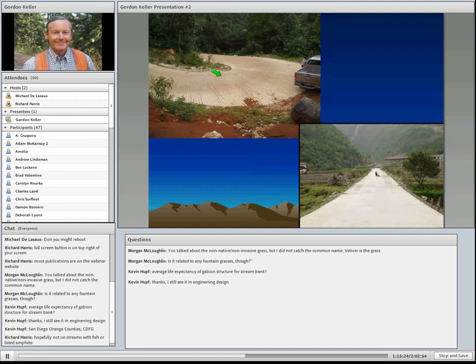Concrete has its place. Some countries use it a great deal. Its best application, for me, is either low water crossings coming through water or on steep grades. If you get into a really steep grade, it's always raveling. You can't hold the surface. Asphalt tends to shove, so concrete works. It's a great solution for a steep grade. If, for instance, you can't keep the grade down and you've got a quarter of a mile section of road that's pushing a 15 or 20% grade, which we normally don't want to build, but you've got them at times, concrete is expensive, but works very well.